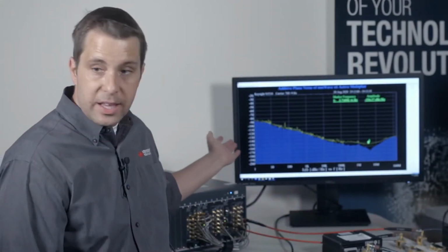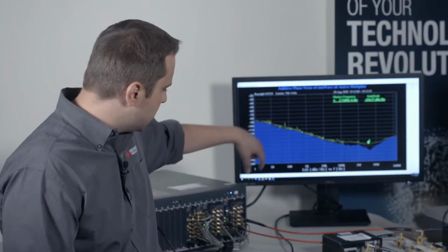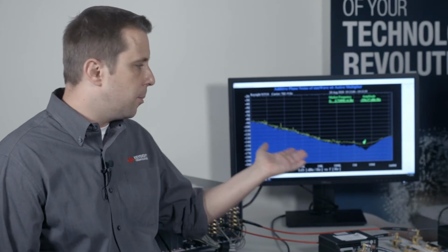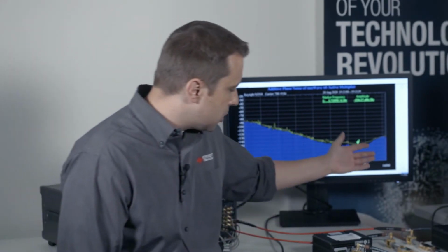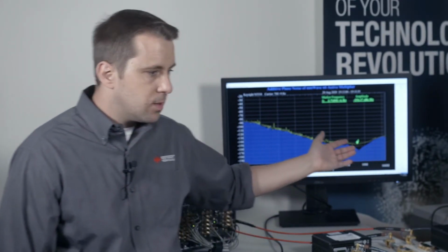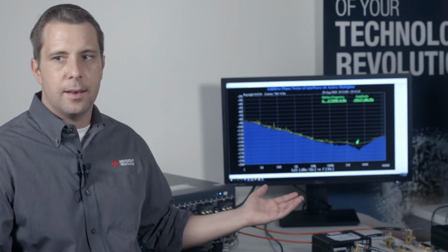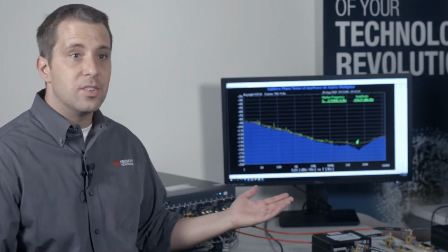Here we have a mmWave measurement set up for PNTS. Internally, we can measure 40 gigahertz, but we have these baseband noise inputs that allow you to add external mixers to go up to whatever frequencies the mixers allow. In this case, we're measuring at 78 gigahertz. And so there's a lot of applications in automotive and satellite and other areas. So mmWave is really hot right now.